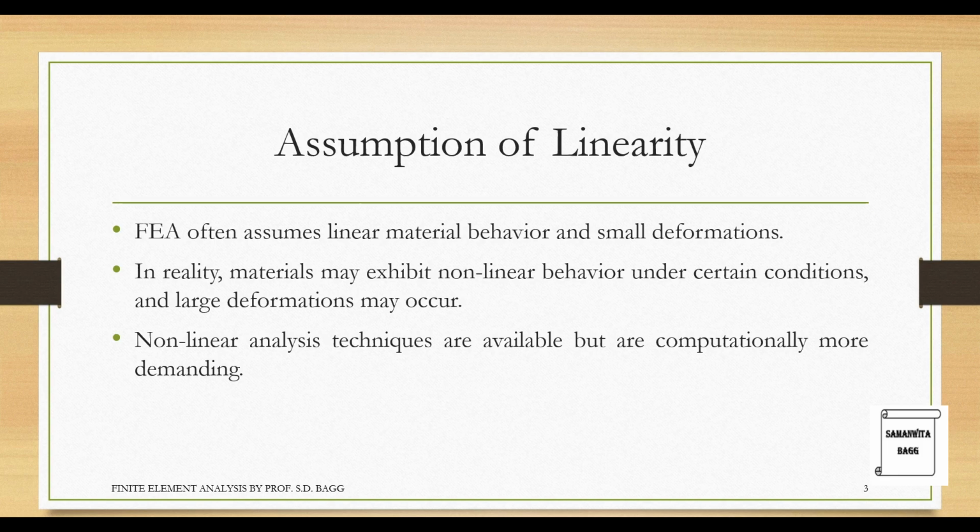Also, in non-linear analysis, there are large deformations that are encountered. You must have seen certain analyses wherein you get an error that there is large deformation and hence you cannot get the solution. At that time, you should give an option to the solver that it should consider large deformation, which means it should take non-linearity into account. So these are certain things which are there in FEA. If you assume linear and go ahead, you will not get a proper solution.